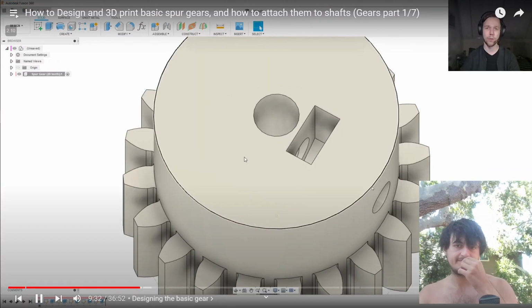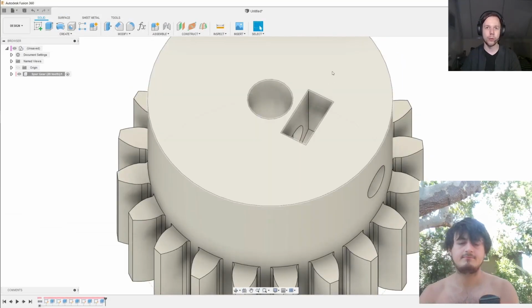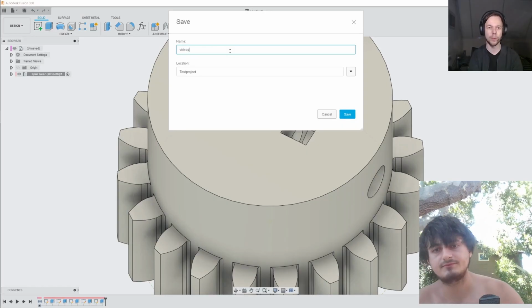That's sick. We have a shaft, we have a hole for our set screw to go into, and we have a cavity for the nut that will accept the set screw. One final thing that I'd like to show you is how you can export this gear as an STL so you can 3D print it. There are two ways to do this, but one way is pretty terrible. The terrible way is to first save your gear, so let's call it video gear, and then...